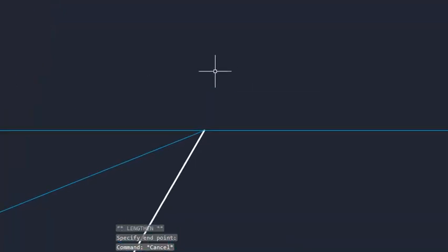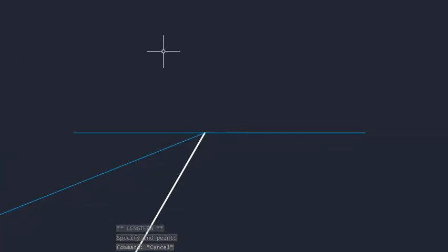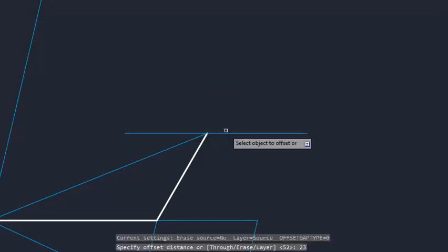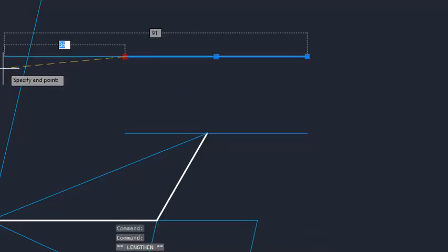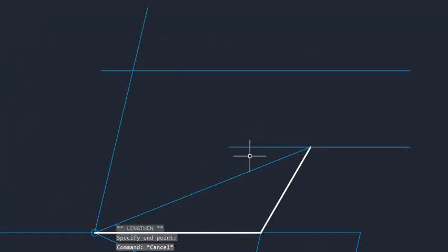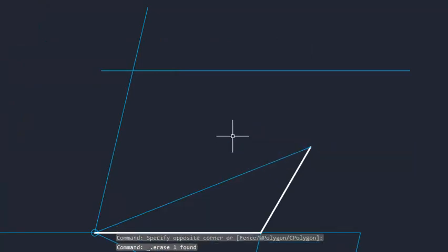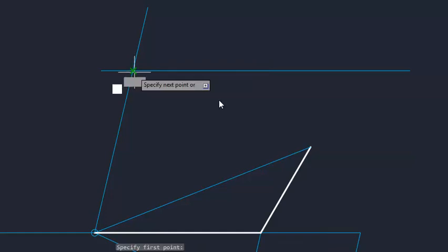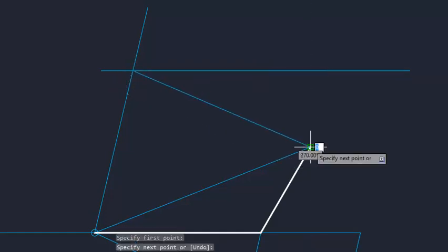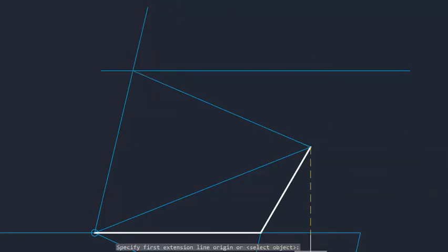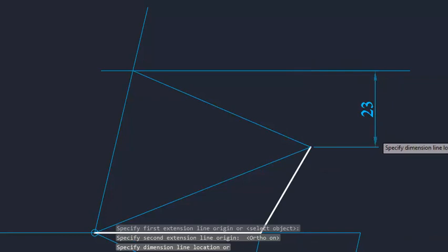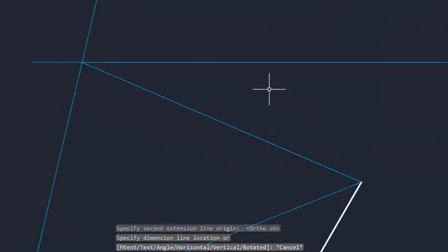Here you can construct another horizontal line parallel to this one at a height which is equivalent to 23. So that's what you do, and the height is 23. You construct another parallel. This parallel will go until it meets the other part of the 55 degree angle. When it touches it, just join up to this point. So at all times, the distance from here up to this point will always be 23, as in part 5 of the question.